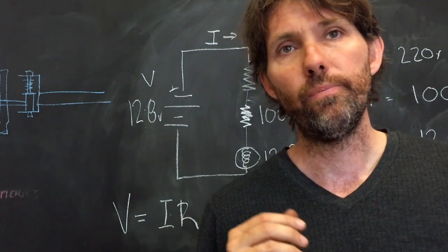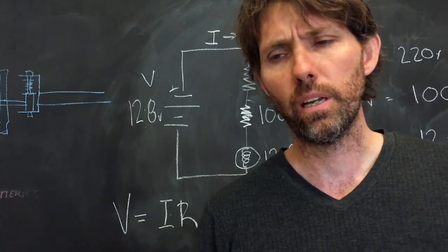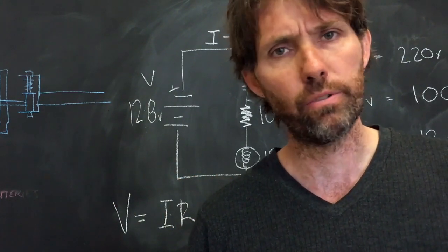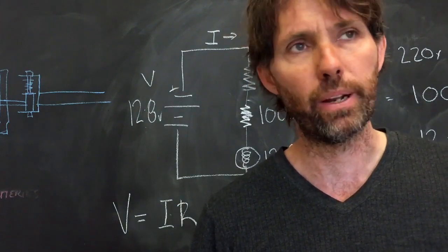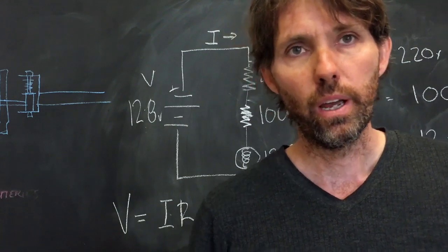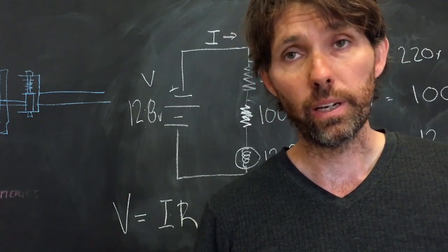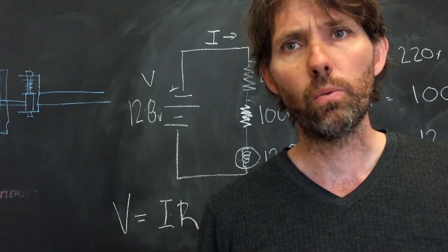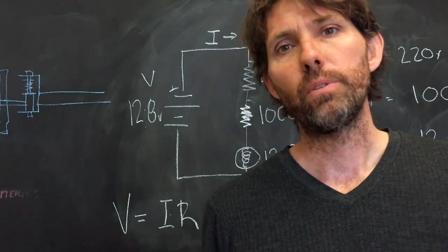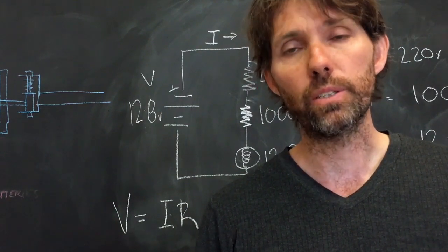So obviously, one thing I will say about this formula is you're not going to look at a connection and go, oh, that's a certain shade of green, that must be a 700 ohm resistance problem. You just know that it's a bad connection and it's giving more resistance than it should. The reason for giving the figures is to show you that it is something you can calculate, but also to show you what a significant effect high resistance has on the voltage that arrives at the lower resistance components.